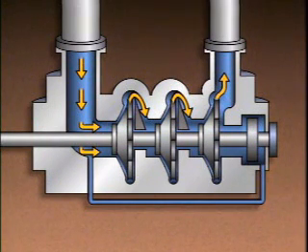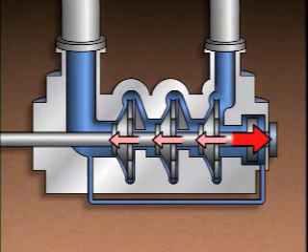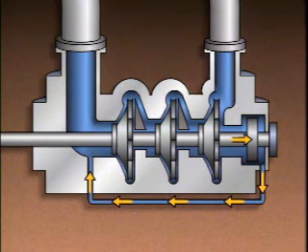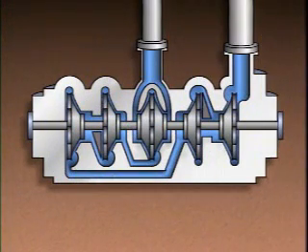During operation, some of the fluid leaving the pump flows along the shaft and exerts pressure against the balance piston. That pressure tends to force the pump shaft away from the suction eyes and reduces the total thrust. Any fluid that passes by the balance piston is returned to the suction side of the first stage. Now on this pump, the arrangement of the impellers is used to offset axial thrust.